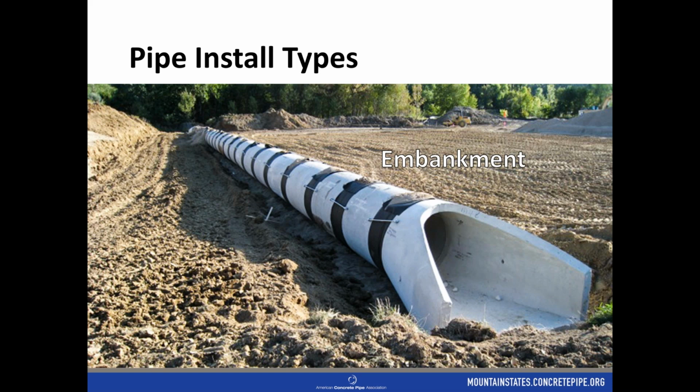Obviously, with the trench, I mentioned that it had that existing ground that has already had time to settle and come to equilibrium there and stabilization. That acts as a friction force to absorb some of those loads and distribute those loads. In embankment, we don't see that. That doesn't happen in embankment conditions, and so that's why it's a little bit more conservative for the embankment.